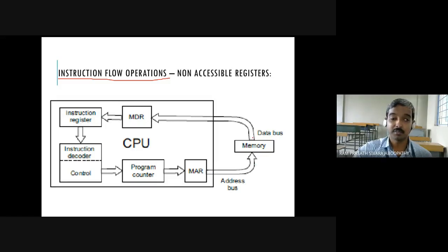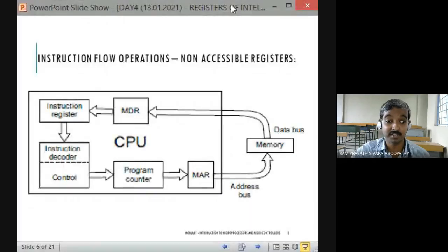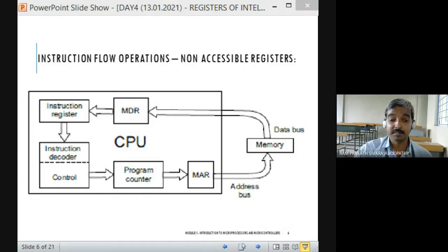Okay, so what about the size of the instruction register? Can you people type it in the chat? Whether it is 8-bit or 16-bit? The value we fetched from memory was 3E. Obviously it is 8-bit information, correct? Yes, Anthony Surya typed 8-bit. What about in the BC and ET class? Kindly respond.